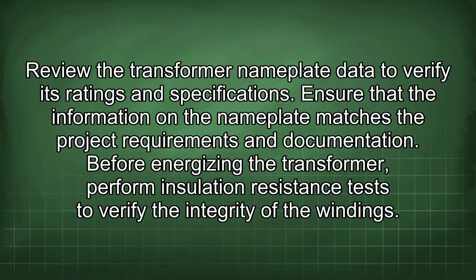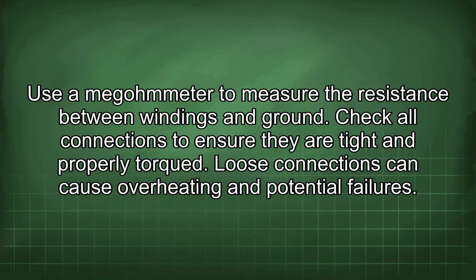Before energizing the transformer, perform insulation resistance tests to verify the integrity of the windings. Use a megohmmeter to measure the resistance between windings and ground. Check all connections to ensure they are tight and properly torqued. Loose connections can cause overheating and potential failures.